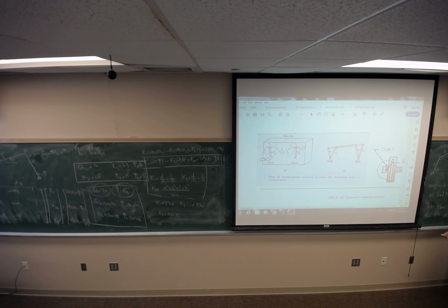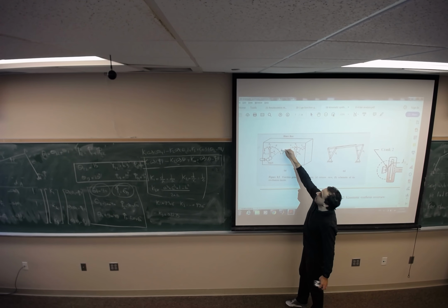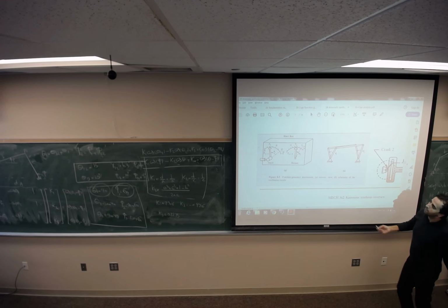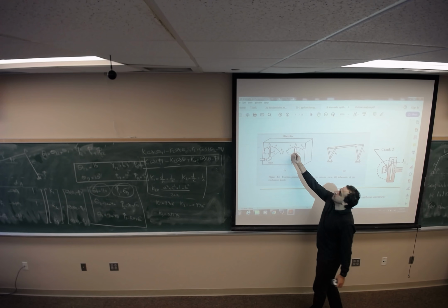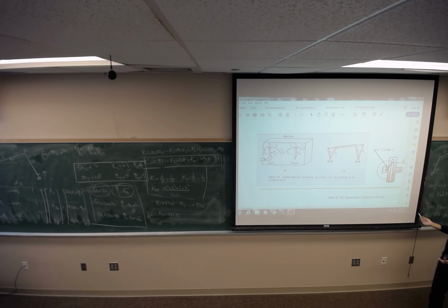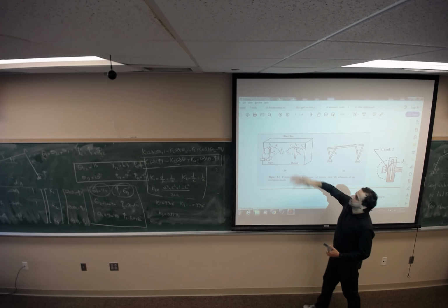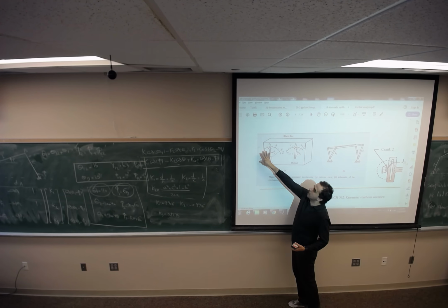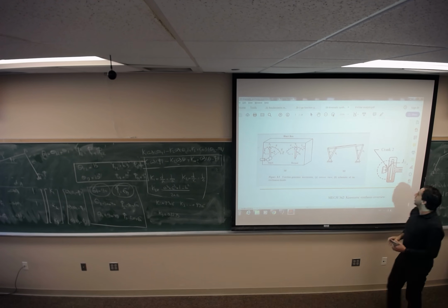We would like, when this arrow is at X1, the other arrow to show us Y1. And when it goes to, for example, X2, this arrow will be at Y2. How can we design a mechanism such that it generates this function? It's function generation because we are given a correlation between the input link and the output link.